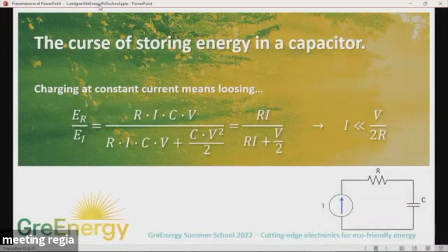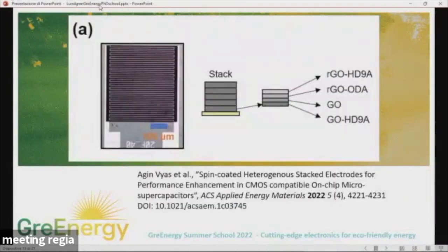So we need to be able to provide high enough current to not just dissipate the power we deliver through that parasitic conductance. So there is a minimum current that we can use to actually be able to charge the capacitor. But the lower we can have the current, the less loss we can have.